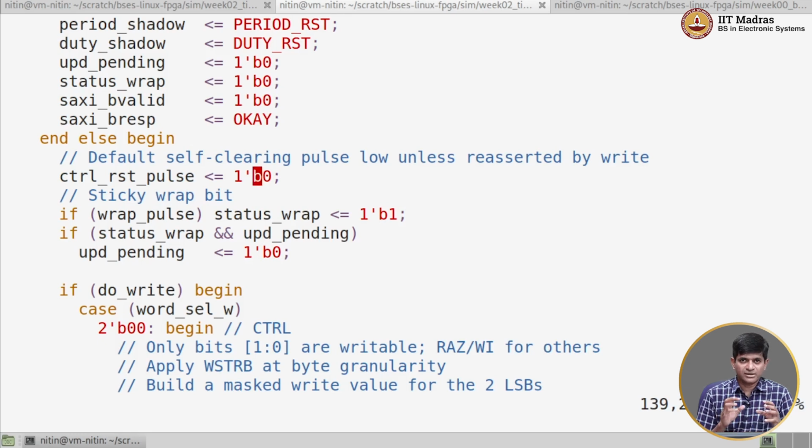In Verilog modeling, each always block and each assignment statement is considered to be operating concurrently, meaning that if I have two always blocks, I cannot be sure of the order in which they are evaluated. But within an always block, the implication is that whatever functionality is desired goes from top to bottom.